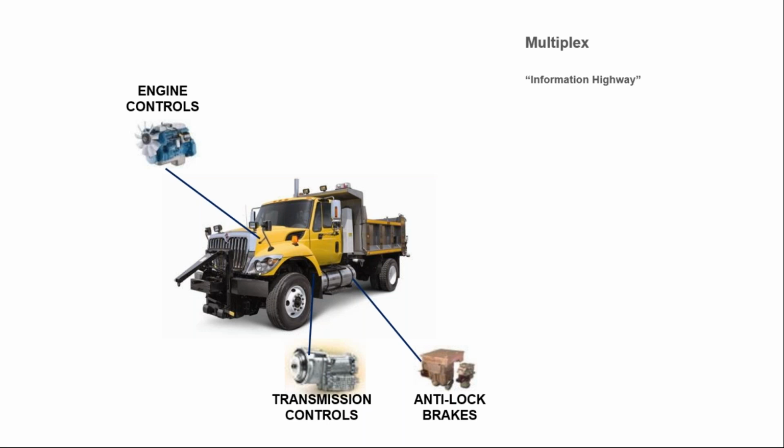If it is an engine with an exhaust brake or an engine brake of any kind, it's going to retain that information and shut off those devices because those could contribute to a skidding event. If it's an automated transmission with a lockup torque converter, it's also going to receive that information and shut off the lockup torque converter, as it also could contribute to the skidding event. So they're all going to share that information. And that's true of all brands of trucks nowadays.